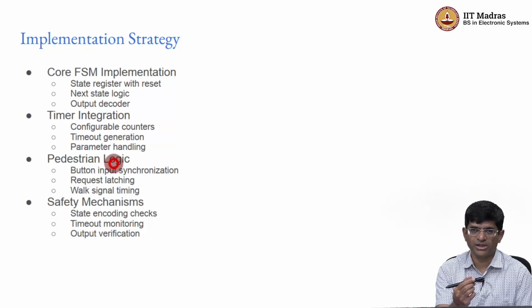So it's too fast for a person to really make out that this is happening multiple times, but well, 10 milliseconds on a 100 megahertz clock is many thousands, possibly millions of clock cycles, right, close to a million clock cycles. Right? So it's not something that you really want to just dismiss out of hand and say, okay, this is not going to happen, right? What we would like is some way by which I can make sure that even if I have a simple problem of this sort, where there is a button that's jittering or vibrating or causing multiple make-break connections over a short amount of time, is there some way that I can actually detect that it was a button press?